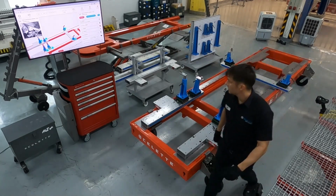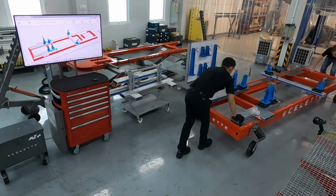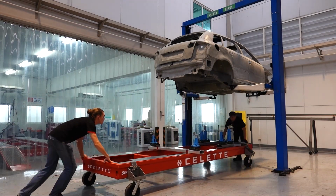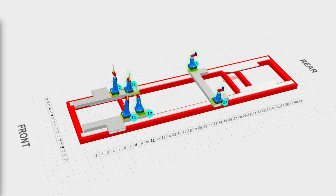And finally, we are ready to bench the car. To facilitate fitting the jigs in the hole when lowering the car, we recommend using only 4 jigs and taking out the pins of the remaining jigs. We will slide them up later into their holes. Among our 4 initial jigs, you can already attach loosely to the car the one with UV socket before lowering it onto the bench.